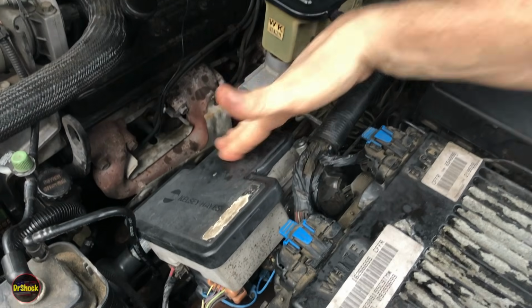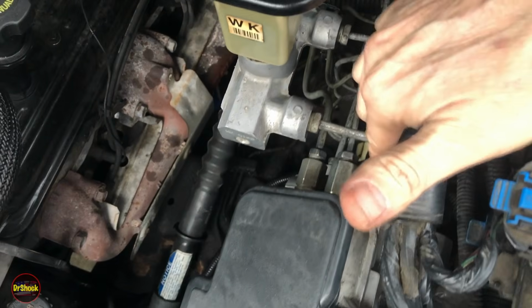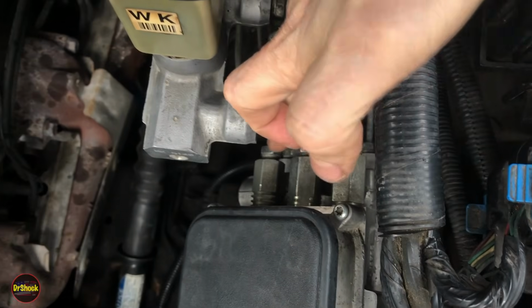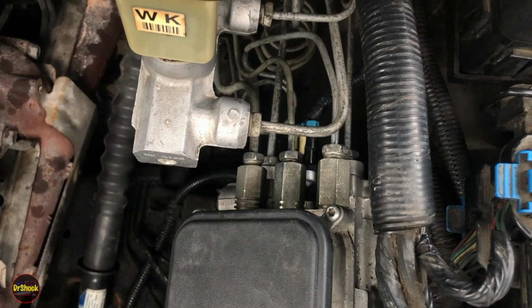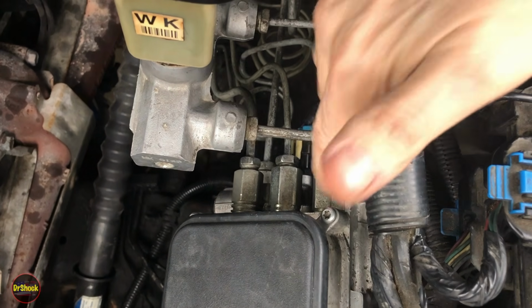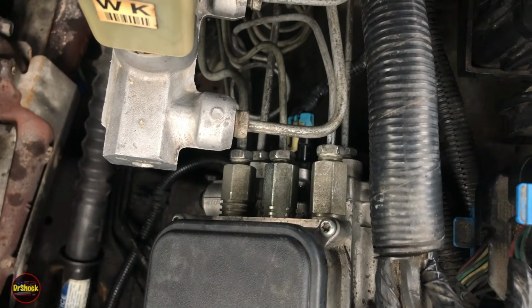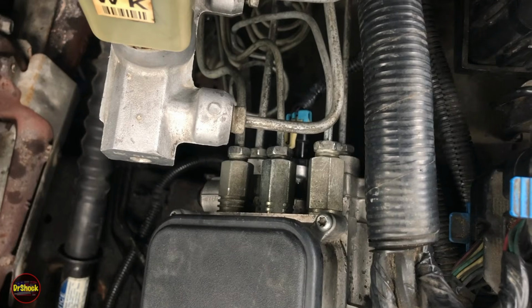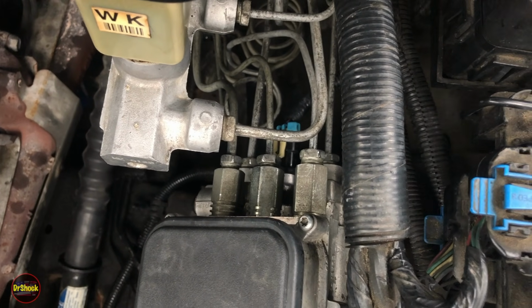When you get the unit reinstalled here, just take note of the fittings. They should be at 22 foot-pounds, each one of them. And like I showed in the teardown video, you want to go through a sequence where you work your way up to that. If you accidentally loosened one of these tubes, then those get torqued down to 23 foot-pounds. If you removed it, you're going to have to find a solution for the O-ring like we talked about in the teardown video.